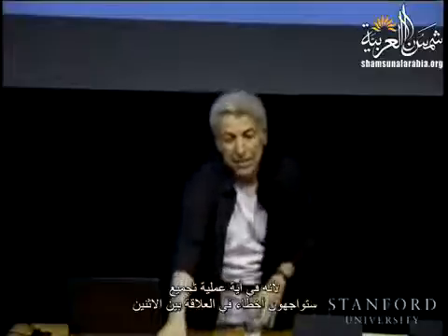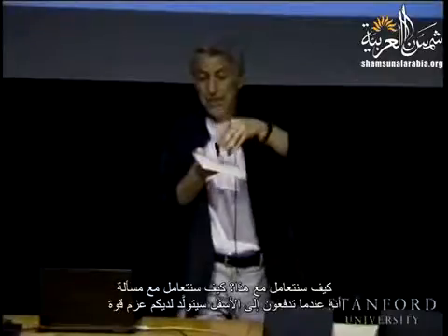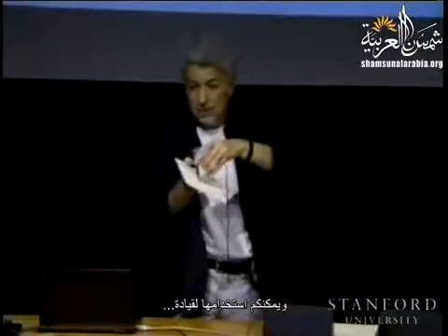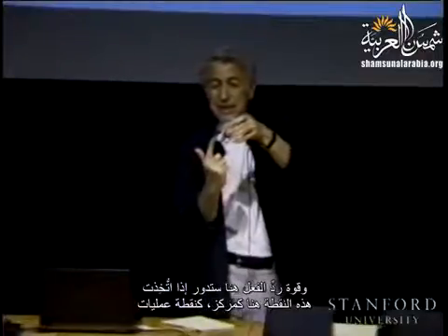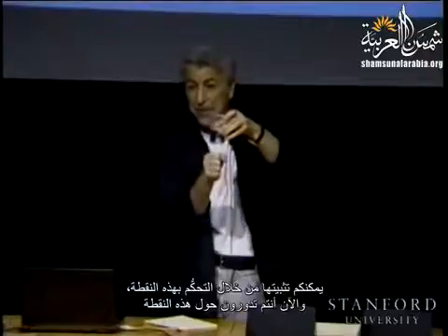Because in any assembly, you're going to have some error in the relationship between the two. How do you deal with this? How do you deal with the fact that when you are pushing down, you are going to have a moment generated? Well, you can use it to drive this rotation. And this reaction force here will rotate if you select this point as your operational point. If you push from here, it rotates. You can fix it by controlling this point, and now you are rotating about this point.